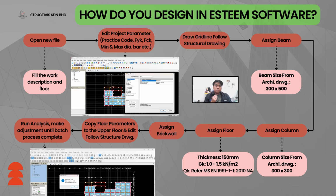Then we can start to draw the grid line following the architectural drawing layout, and we can assign the beam. So first we use the architectural drawing where we propose the size of 300 times 500 for the beam. Next, we can start to assign the column, where we use the architectural drawing layout using the 300 times 300 column size. After that, we assign the floor with the thickness of 150 millimeter